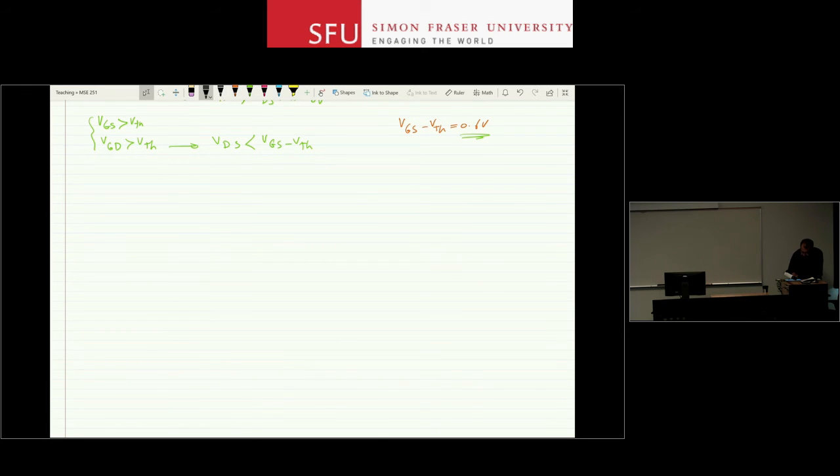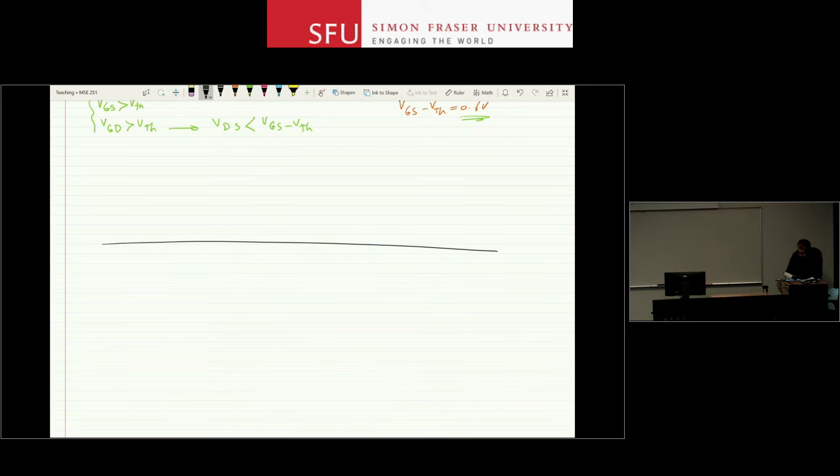Well, structurally it is very similar. So I have again a substrate that is N-type in this case, and I've created my doped regions by inverting that N-type into P+, then put down a dielectric and cover that dielectric with a conductive material, right? So this is my gate, let's say source and drain. Very, very similar to what we had for an N MOSFET.